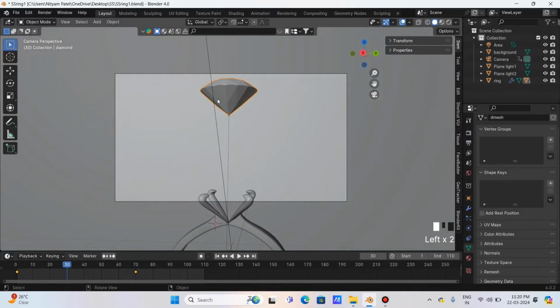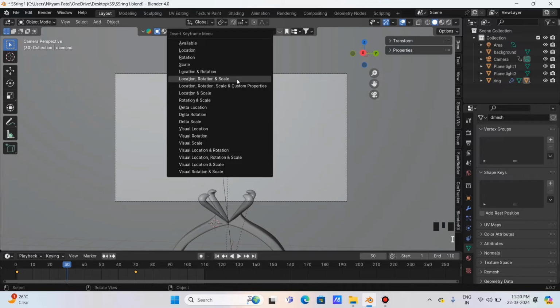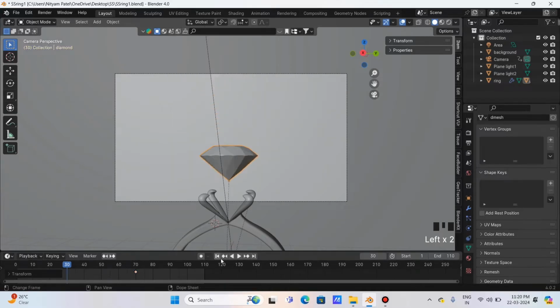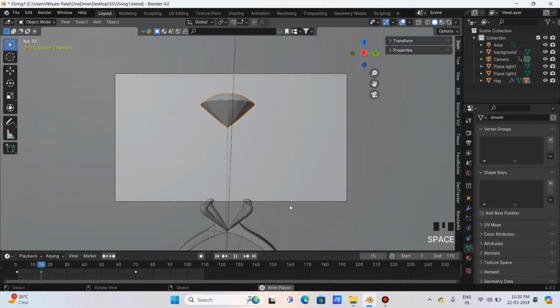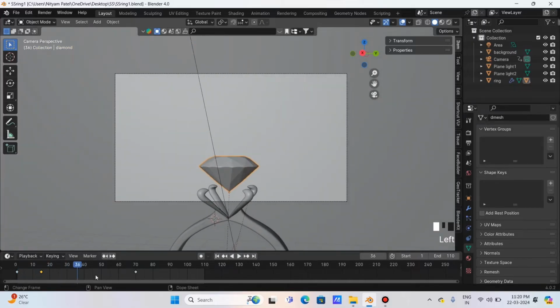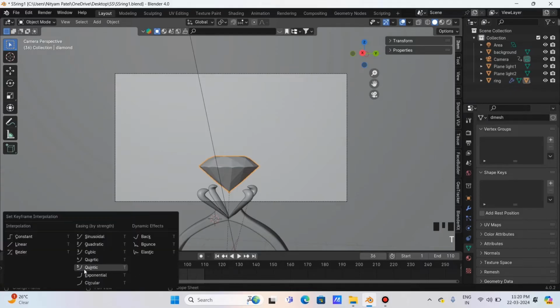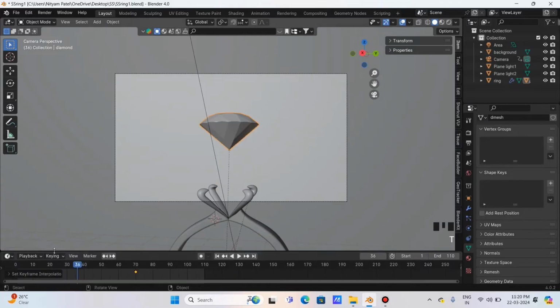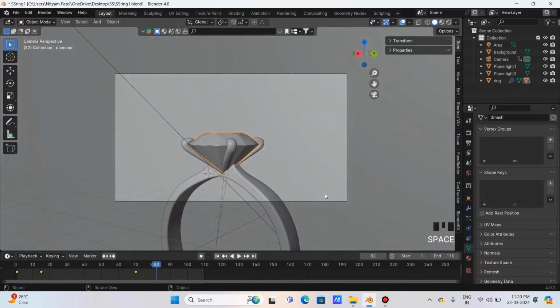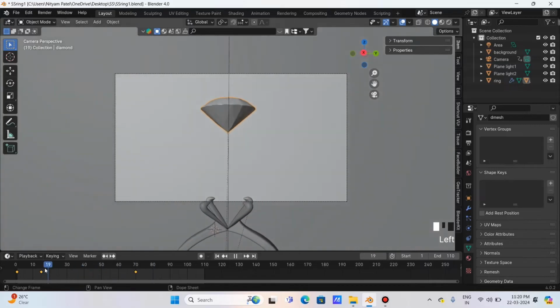And here I want the speed to go from fast to slow, so what I do is at frame 30 I give the keyframe and drag it to frame 15, so whatever happens in frames 1 to 30 will happen in 1 to 15. Basically it becomes fast, and by pressing T on the timeline I select linear, so it gives a constant movement. Like 1 to 15 is much faster and then slow.